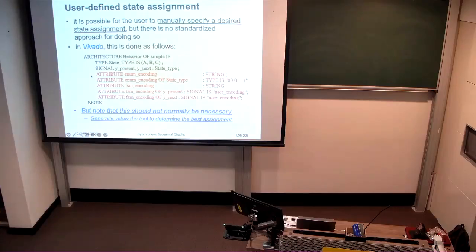You've only got a shift register effectively that you're moving states between. So the logic is simpler, and because the logic is simpler, it requires less hardware, and therefore it's faster. Okay, so that's another benefit from that.